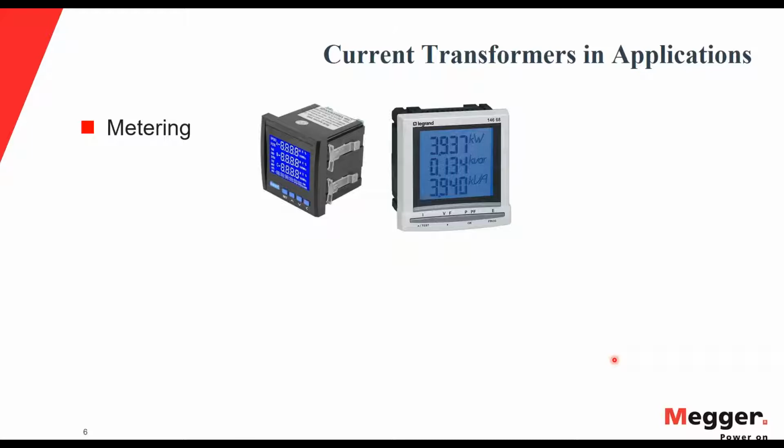And you want to have as much accuracy as possible within this range, because especially for energy meters, any errors coming from the CT side will directly transfer to losses in profits or metering revenue and so on. So it's a direct money loss, or direct energy not counted or counted, depending on what the error value is from the CT.